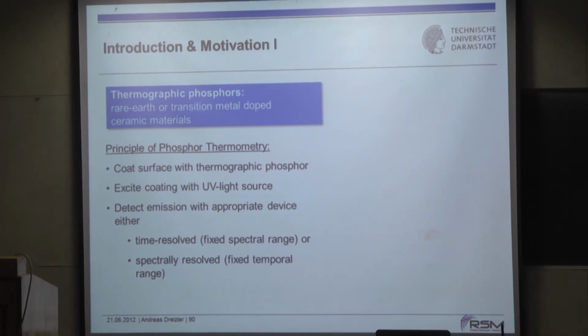Yeah? But be careful. If you have a ceramic that is maybe only 10 microns thick, it is an insulation layer. Yeah? And so this is not non-intrusive. At least you can say it's semi-intrusive. And if you do have a strong temporal variation, intermittency, then that might have a huge impact on what you're doing. And so be careful.